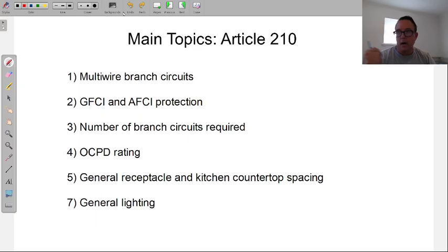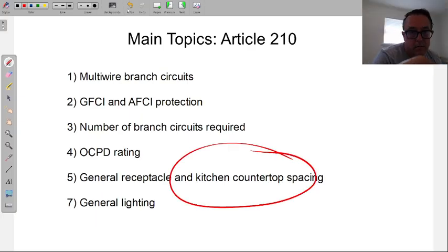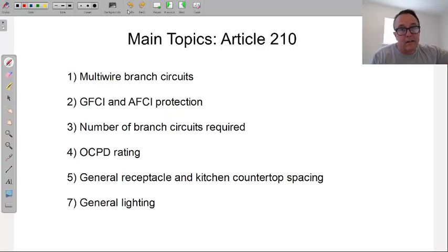This is why they space the outlets in a particular way, because the cords are a specific length. For example, lamps, TVs, things like that generally come with a 6-foot cord. So that's kind of the spacing for outlets in a wall. 6 feet, and then when we get to a corner, it becomes 12. We'll get into all the dimensions, not to get too deep into that right now. Different from counters. The countertop and things that go on the countertop have a shorter cord, 3 feet. Blender, microwaves, things like that.